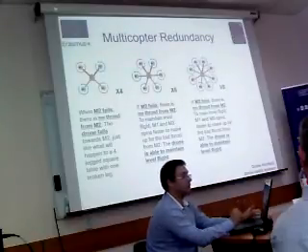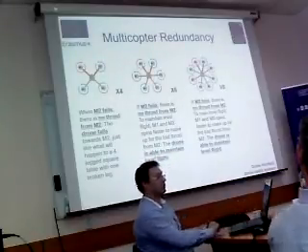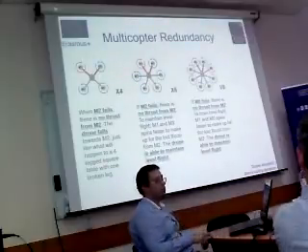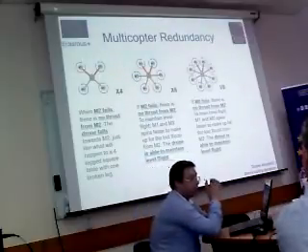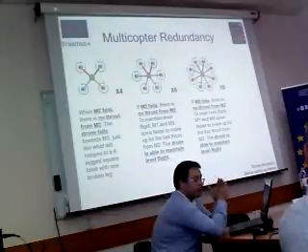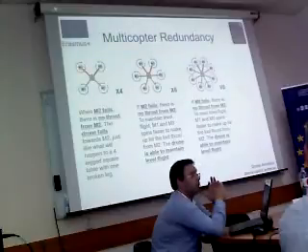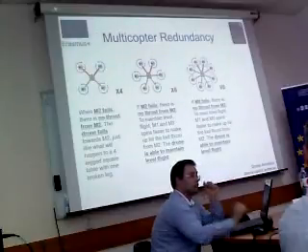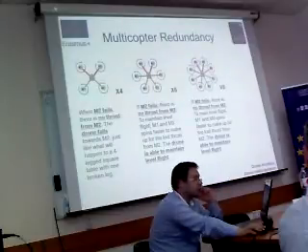So the platform has a net clockwise moment and it will start spinning in the clockwise direction. But in modern drones, with an intelligent course-lock feature, the drone will still be controllable by a moderately skilled pilot, since the computer on board will take the pilot's input commands and transform them into actual commands relative to the drone head.